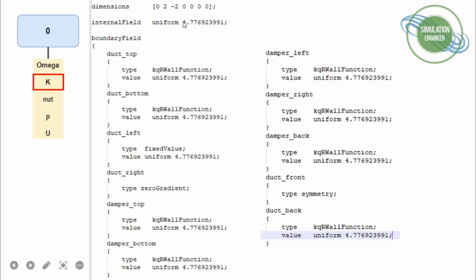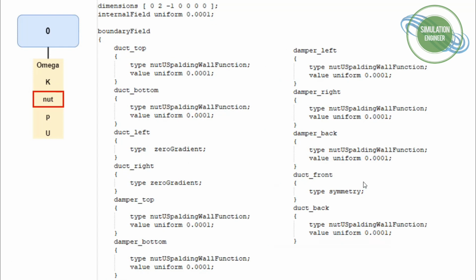Similarly, we'll be using our calculated value for our initial conditions, and we'll stick with the same approach for all the no-slip wall boundary condition patches. We will define the wall function as a type, and we will initialize the inlet patch with the fixed value, and the pressure outlet, which is the right part, as zero gradient, and symmetry will stick with the symmetry part. And now we will move on to the eddy viscosity, so nu T.